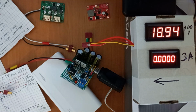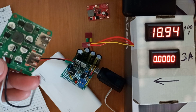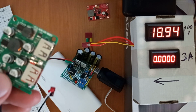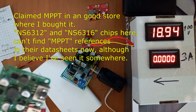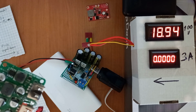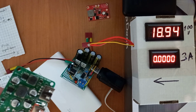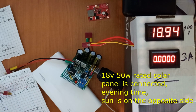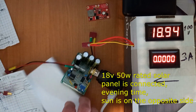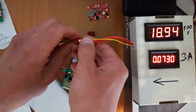Now about the incorrect work of this claimed MPPT device, and it's also claimed in the datasheet of this chip. It just works as a plain buck converter and drops the 18 volt panel voltage to 5 volt output, resulting in something like 30% generation when we're talking about 18 volts. I'll connect solar to my device first to show how it should work.